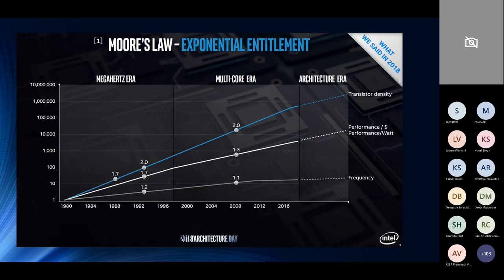And again, there are a lot of reasons behind it. As and when you shrink the feature size, you are dealing with maybe molecule level accuracy. If that is the case, it's extremely hard to control such structures on silicon wafers, right? So your yield gets impacted. So you may not be able to push the density the way you used to push before.